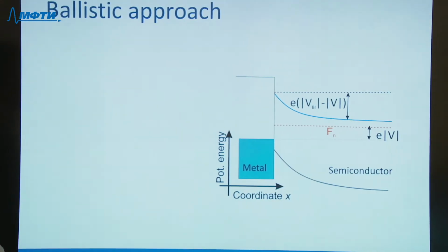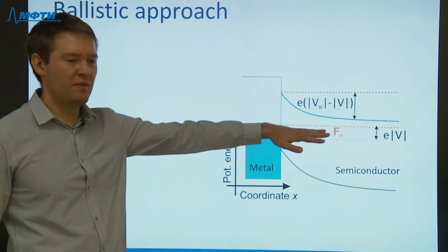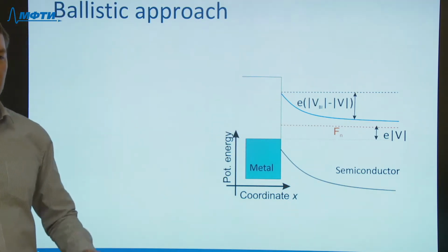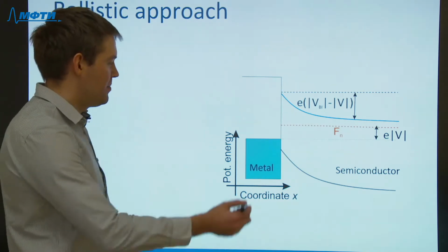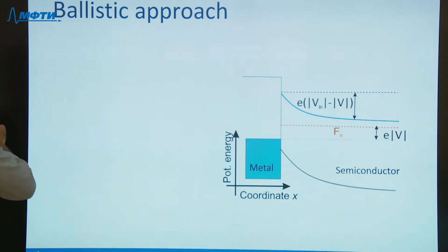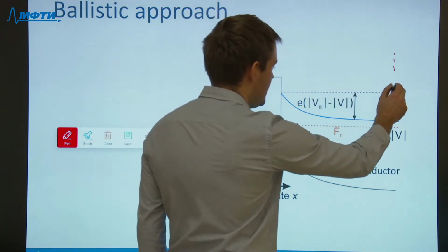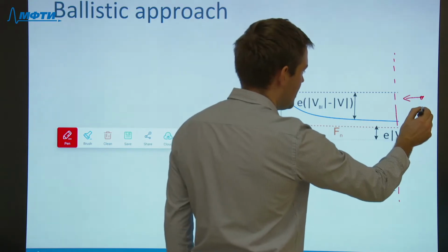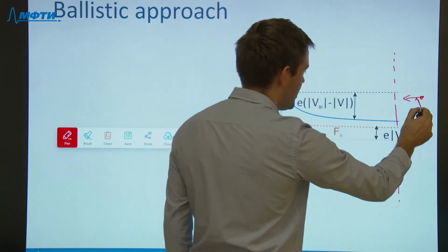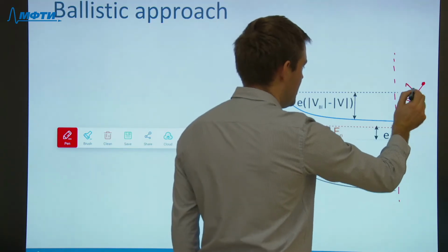When we consider ballistic transport, the concept of quasi-Fermi level becomes not much important, because the equilibrium between charge carriers is only somewhere deep in the contacts, where the carriers can collide with each other quite frequently, and this can lead to thermalization.